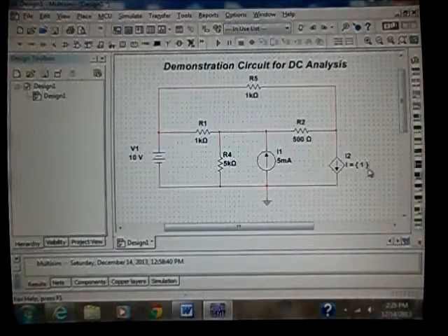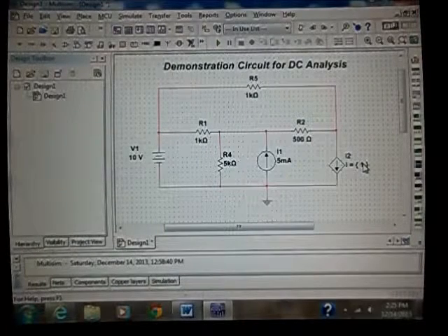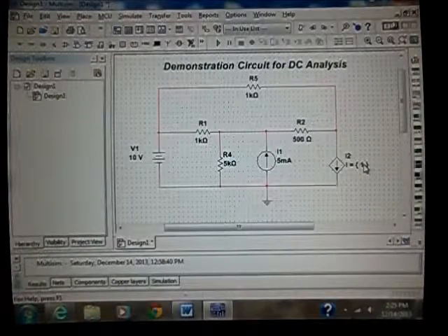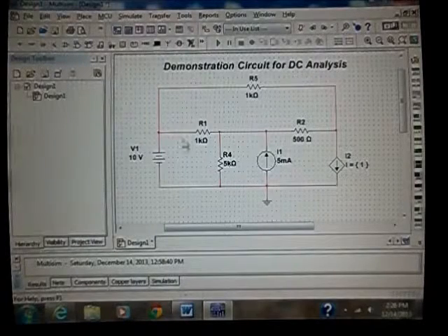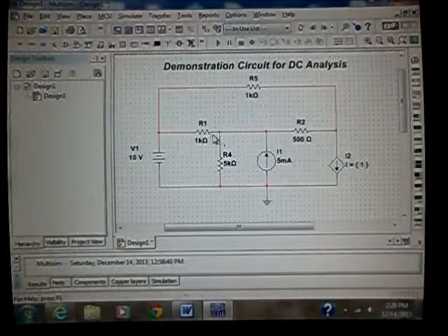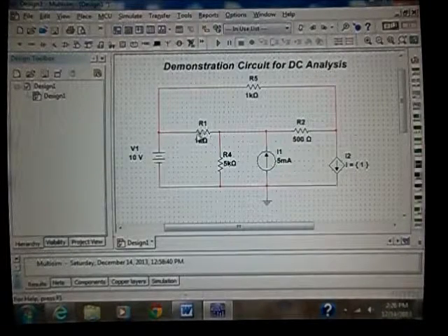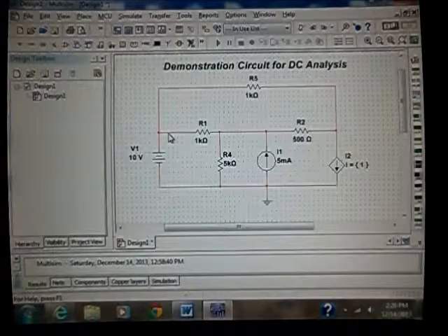And now it's time to do the harder part, which is to set the strength of the ABM source to make it into, say, a voltage-controlled current source. To do that, let's just say I want to get the voltage plus to minus across R1. How do I indicate that? Well, I'm going to have to find out what these nodes are named.